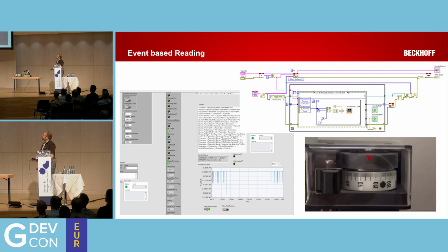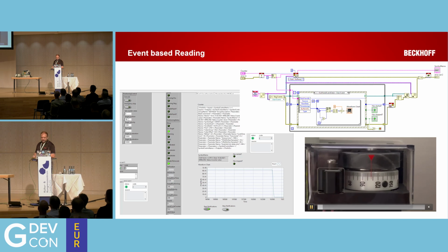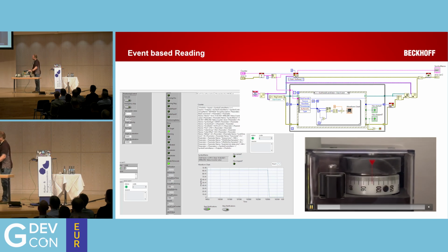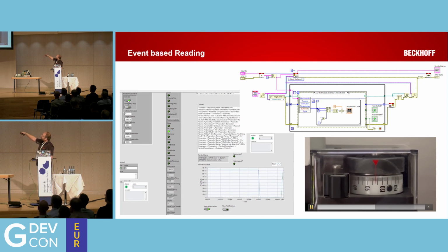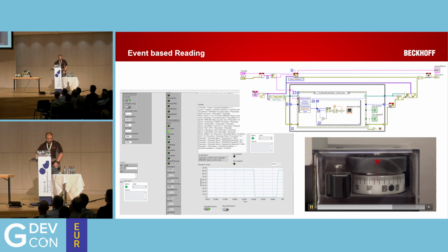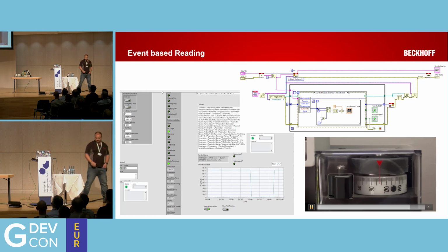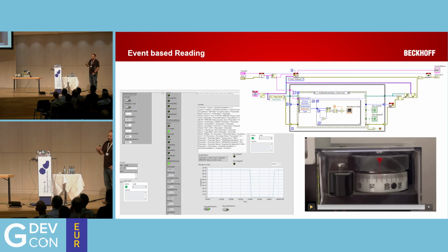going on here. So what's actually happening, if I can start both videos at the same time, if it will allow me the pleasure, hold on, is we have the motor rotating. Where's my mouse gone? There it is. And as the motor rotates, there's a sensor on the system that is a counter module, and that is then being updated by this system of event-driven reading. What that basically does is the LabVIEW interface allows you to put a notification, either cyclic or on change, on the variable you're interested in reading. And it will just push data to your client that you can then bring in.